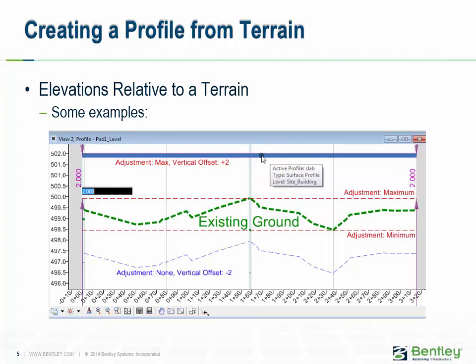Profile from surface allows a variety of profile options draped from existing ground, and the profile geometry settings can be edited in the element information dialog or via the context-sensitive heads-up display prompts. Geometry relationships are held, so if the terrain model has a change, then the profile created will adjust accordingly.